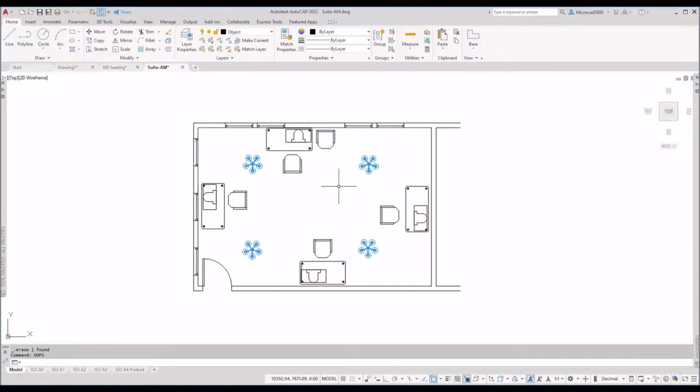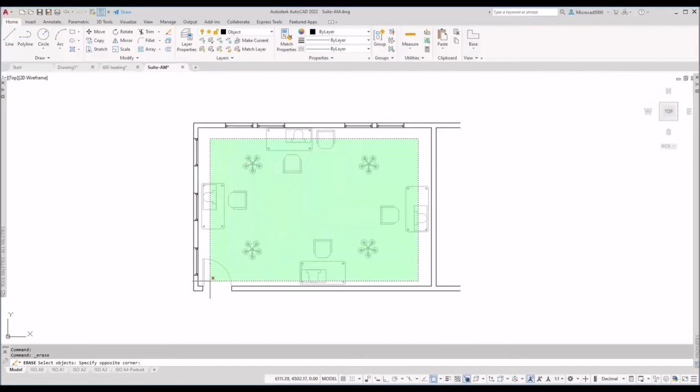So yes, if you're like me, when you're working in CAD, there'll come a time where you'll pick some objects, maybe a difficult selection set, and an item you didn't mean to select. So there I'm going to wipe out all the information in the middle of the room. So I'll click everything, then I realise, oh, I've picked the door as well. I didn't really mean to pick the door. So I need to deselect the door. Now if it's just one or two items, just hold the shift key down and pick on the door there.